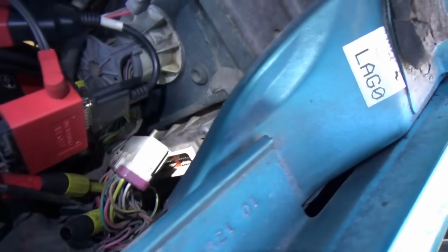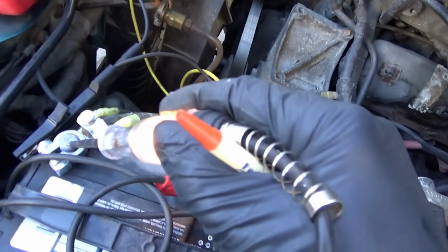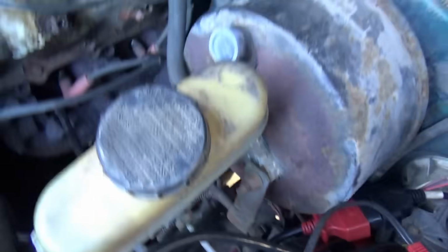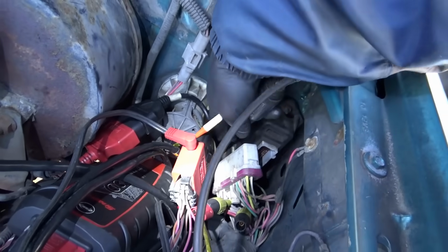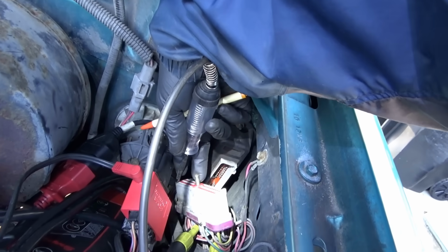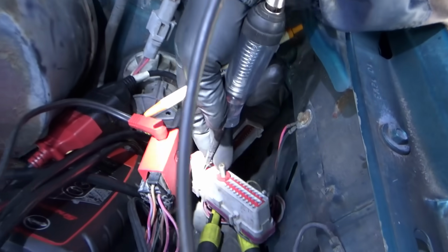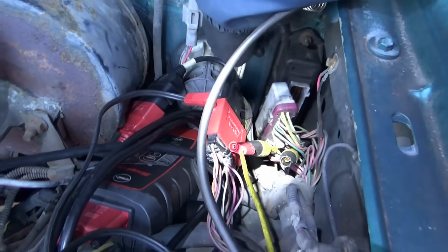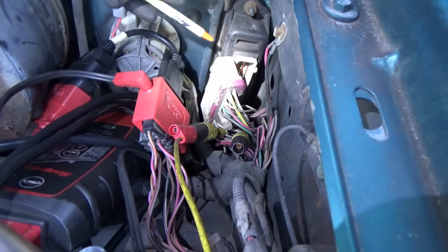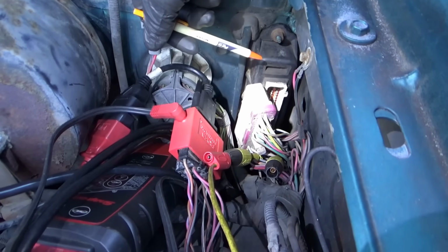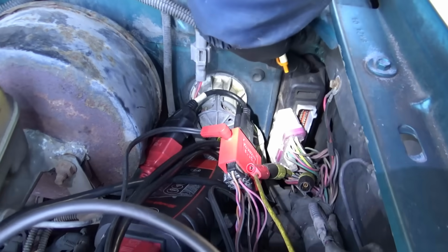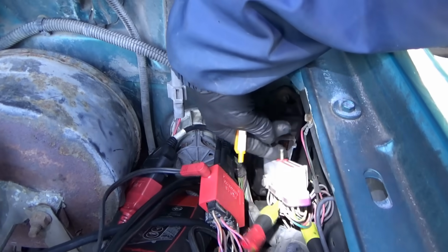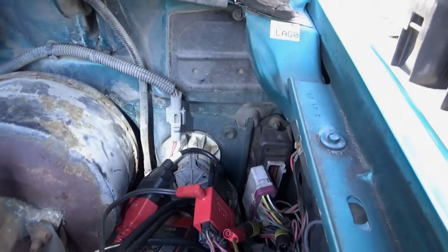So we got the PCM unplugged. Connector looks mint. Just doing some powers and grounds. So there are 2 grounds here. The orange wire down there and black and green, and they both check out. So not worried about that one or that one. Powers are obviously good, you know, computer's alive. That's it. I mean, we could take it out, see if there's anything interesting in there on the board. Doesn't seem too hard to get to. One bolt here. There might be one down there. I don't know. But it's looking like just a bad engine computer.